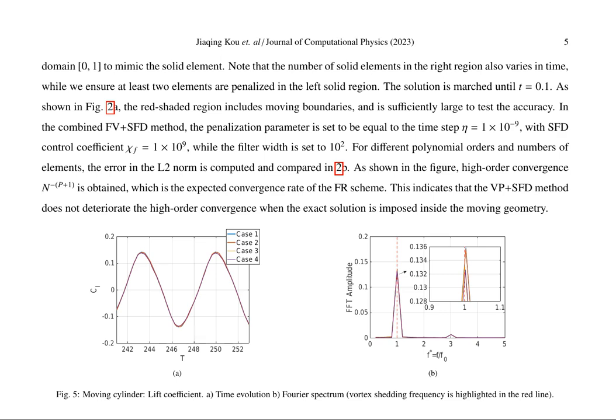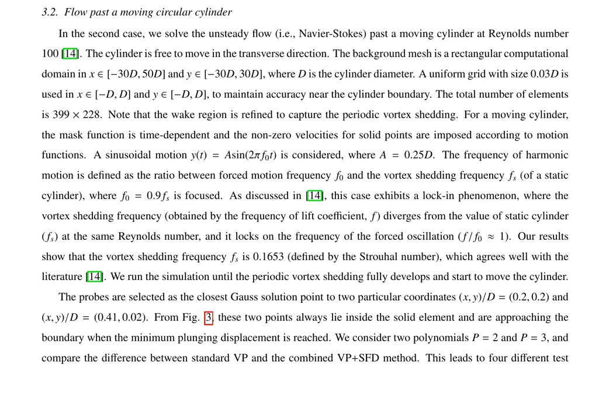The paper discusses the extension of an immersed boundary method, which combines volume penalization and selective frequency damping (SFD), to simulate fluid structure interactions involving moving geometries. This method is designed to enhance accuracy in imposing boundary conditions within high-order flux reconstruction schemes. The approach decomposes the numerical solution inside the solid into a predefined movement and an oscillatory part, with the latter being damped by the SFD technique.